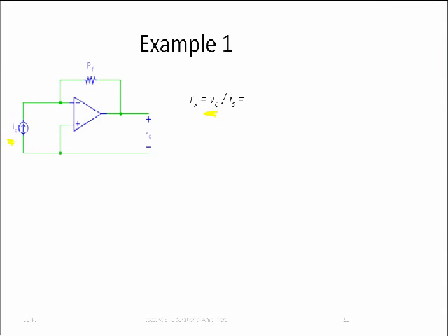If this was a light switch, we put a little bit of mechanical energy in, and then we get a lot of electrical energy out. So in this particular case, the input happens to be a current, the output happens to be a voltage, then the ratio, of course, is a resistance. This is not a physical resistor, but this whole circuit synthesizes a resistor, and we call that resistor Rx. Okay? Can do that.